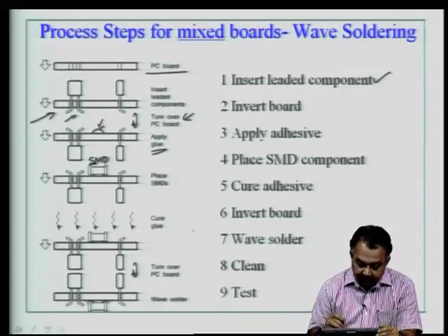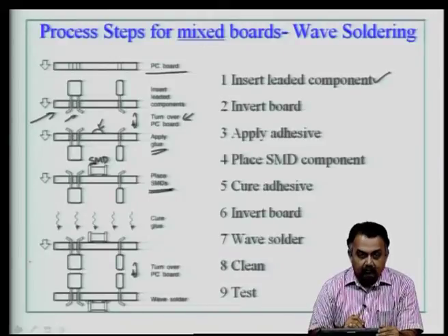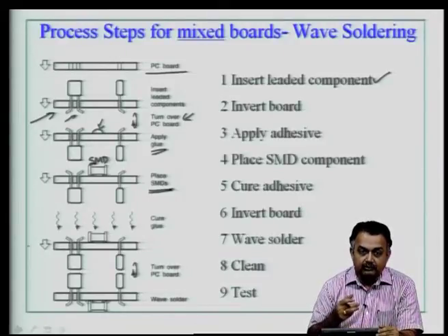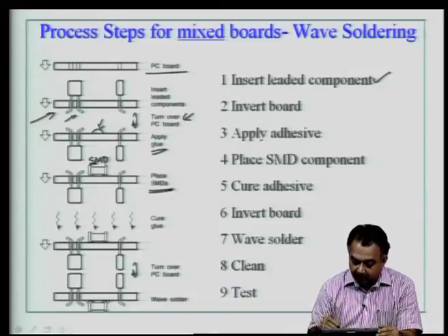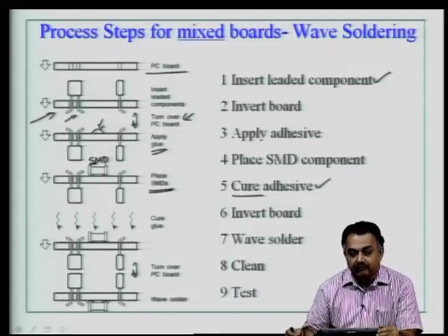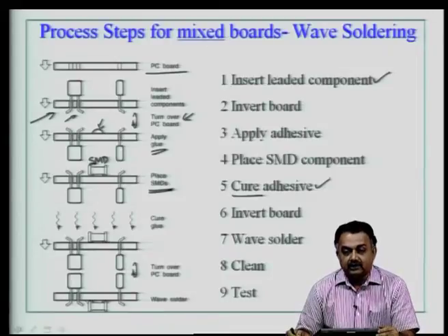So, once the SMDs are placed, what you have to do now is to make the SMDs secure in their place by doing a curing process. You have to cure the adhesive at certain temperatures.